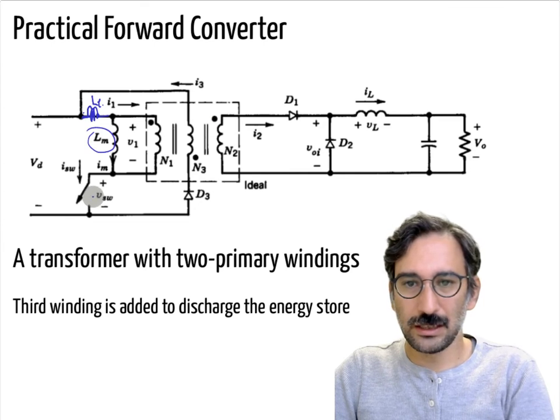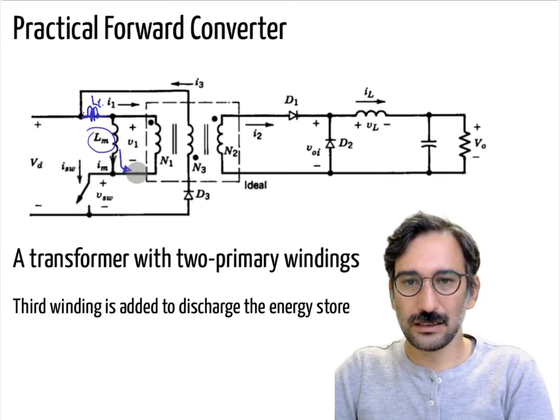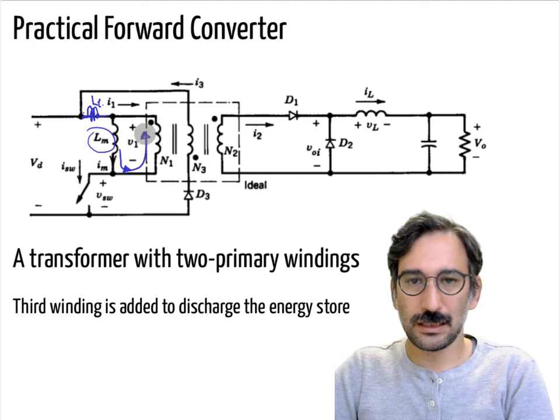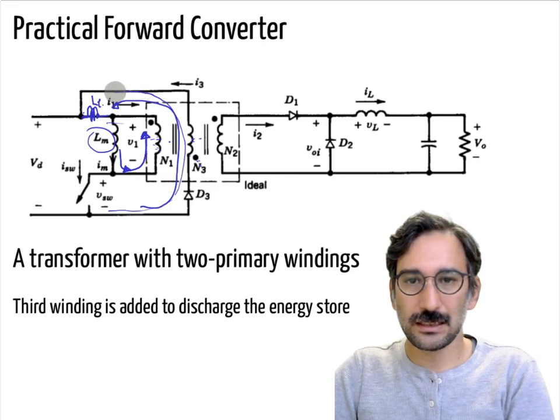But whenever that one is off, you want that inductor current to flow somewhere else, and it is flowing through that one. While it is flowing through that one, you have a turns ratio, and that is creating some path through here. So using N1 and N2 terms, you can send the energy.